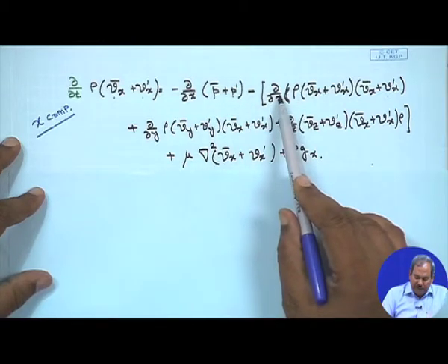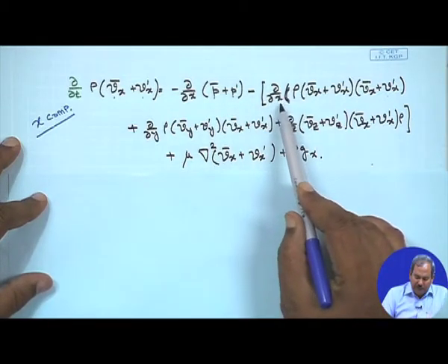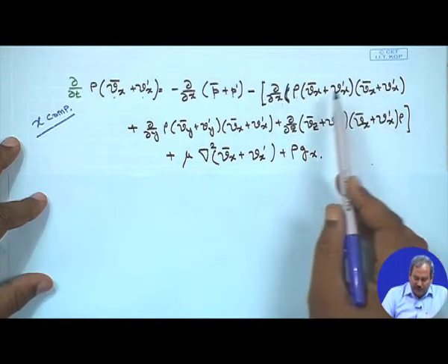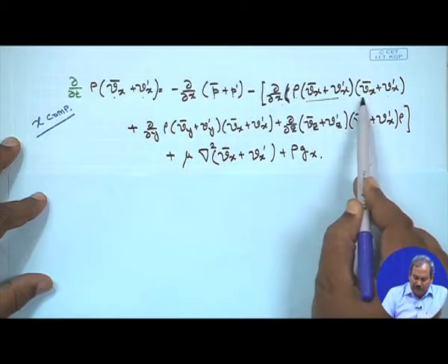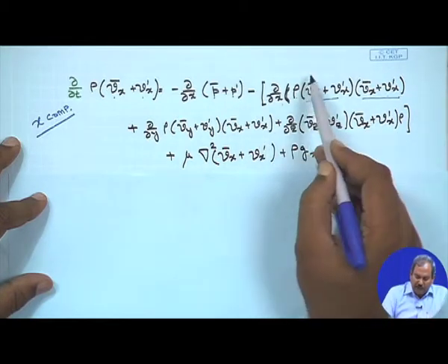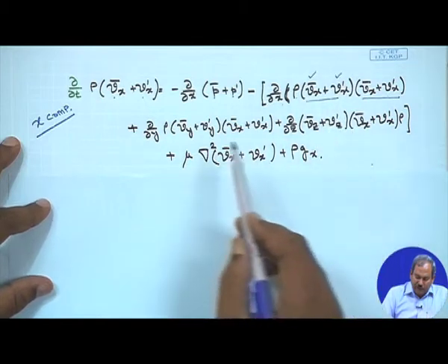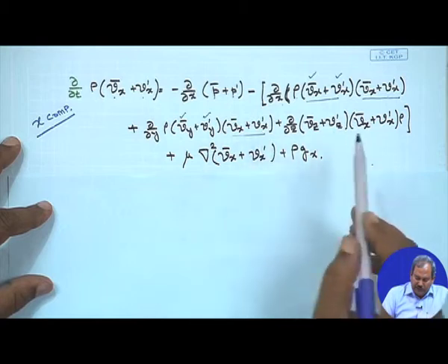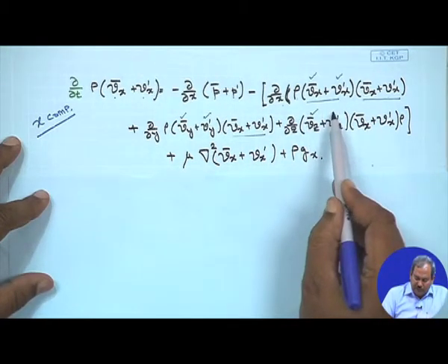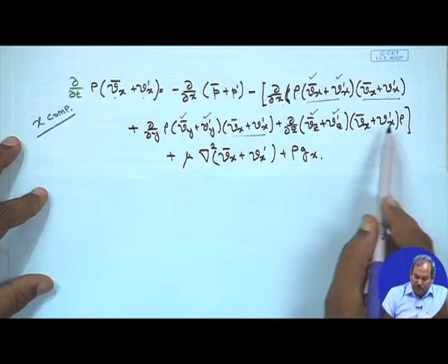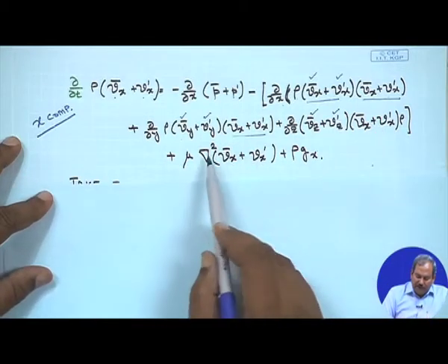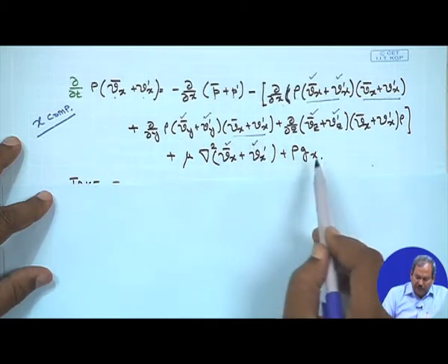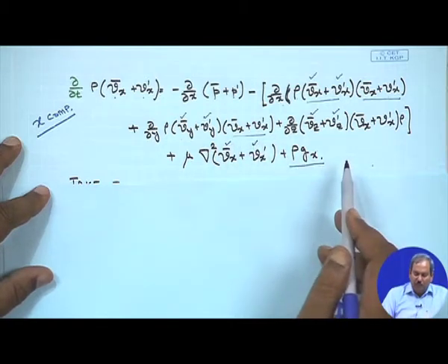So, the other terms are going to be del x of rho Vx times Vx like before, but the velocities are now expressed as the sum of time smooth and fluctuating. Similarly, for Vy, time smooth plus fluctuating, this is the same. For Z also I can have the sum of time smooth and fluctuating, and the shear stress term will also have a time smooth and a fluctuating part, and I have the normal body force.